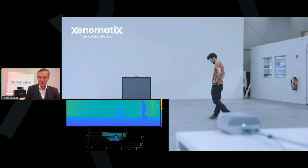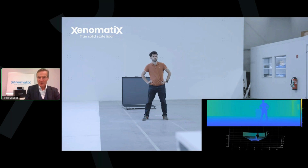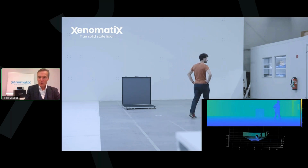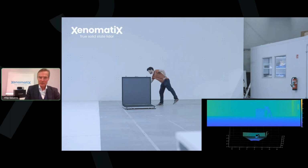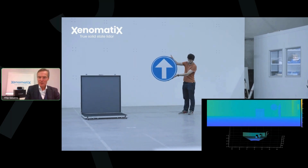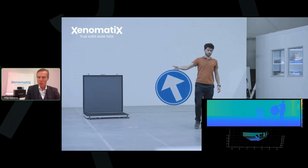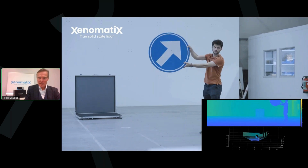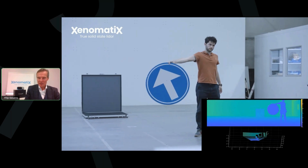Maybe this was still easy, and we show you just to give you an impression on the quality of the point cloud, but let's crank it up and let's make it a lot more difficult. Now, next to the low reflective target and the person, we will bring in a reflector. A reflector being a traffic sign, and a traffic sign actually has a reflectivity of a few thousand%. So it returns the light more focused than the way the light hits the target. Bringing a reflector, a traffic sign, so close to a LiDAR is challenging.